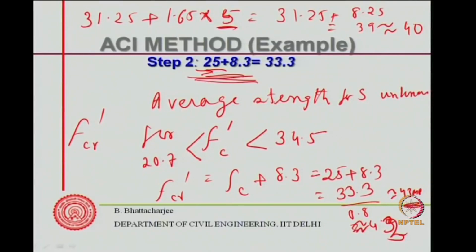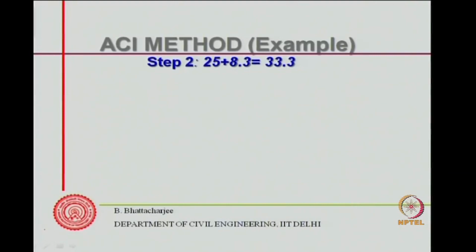So, you see this is taking slightly higher if you look from the Indian standpoint, this value is slightly higher. However, step 2 is because this is unknown. So that is why it is taking slightly higher, but if the standard deviation becomes known, then this would become lower, because we said that it will be f c dash plus 1.34 into s.